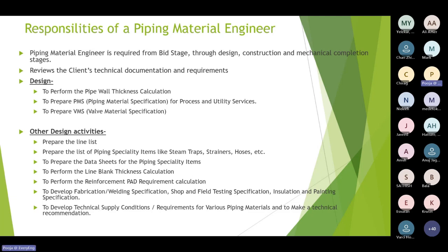Then, as we say, for certain fluids, certain material is suitable up to certain temperature and so on. So accordingly, in the bid stage, we look at what fluids and chemicals are included in that plant. Accordingly, we select the correct pipe material, or we prepare the piping classes. Then we take out the bill of material, just like if I want to buy a house, I have an estimate of how much cement I require. So accordingly, we give this estimate to the client.